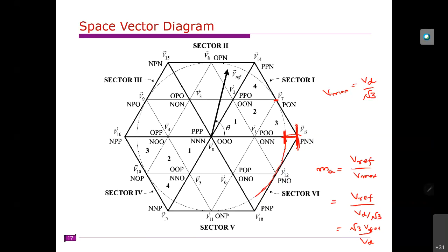In some cases, we define it in some other way: this entire thing, starting from here to here, is sometimes defined as the modulation index, usually capital MA. Here they define the linear range from here to here, and onwards is the non-linear range. Okay, so just ignore this one. In most cases we define this one as the modulation index, so that we can easily identify the linear range. So 0 to 1 is the linear range, and beyond 1 is the non-linear range of the modulation, right?